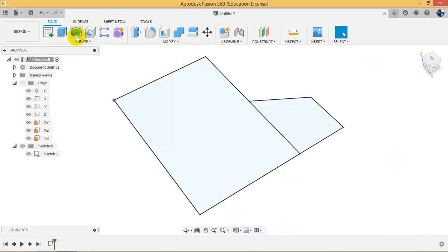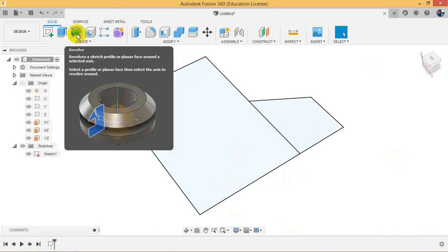What this does is create a 3D shape, you can see in the picture, from a cross section and an axis. That cross section is a profile, and that axis is the axis of the turn, and you can create that shape by just selecting those.